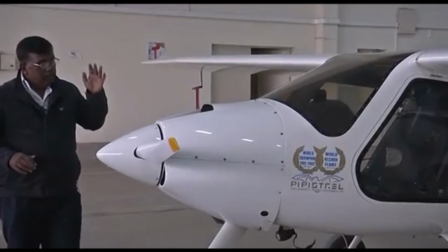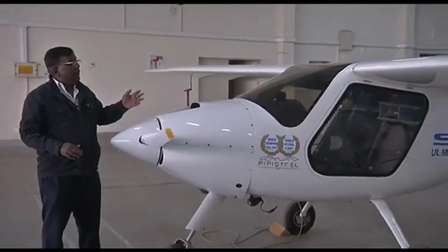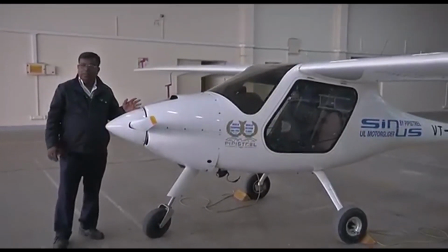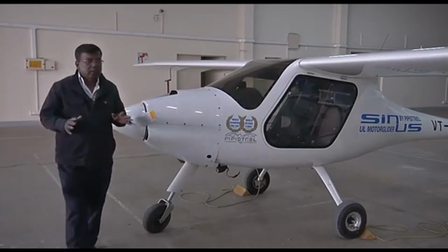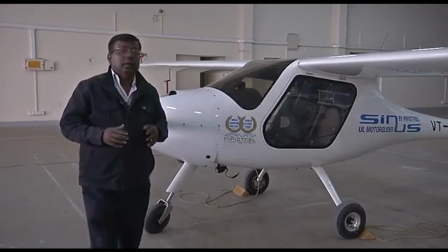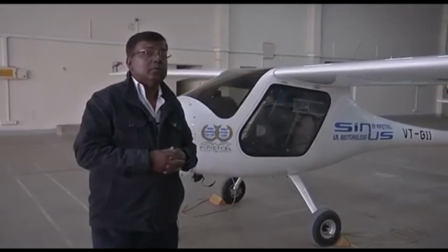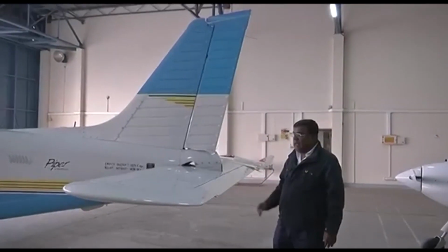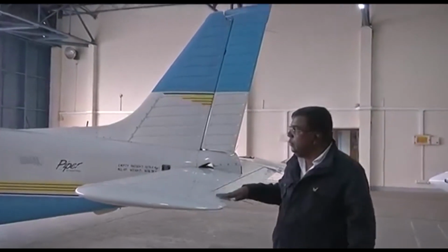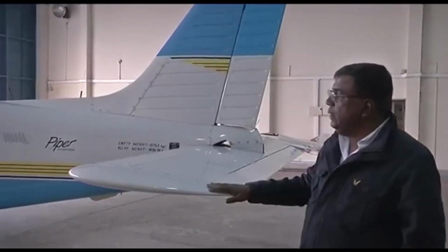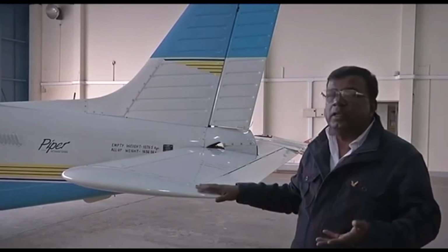So wing, this is the propeller, horizontal tail you already know, landing gear we have discussed, and that makes the whole understanding of static stability. That also makes us understand who contributes what. To conclude, we see that the horizontal tail primarily contributes to longitudinal stability, and the wing has a marginal effect.